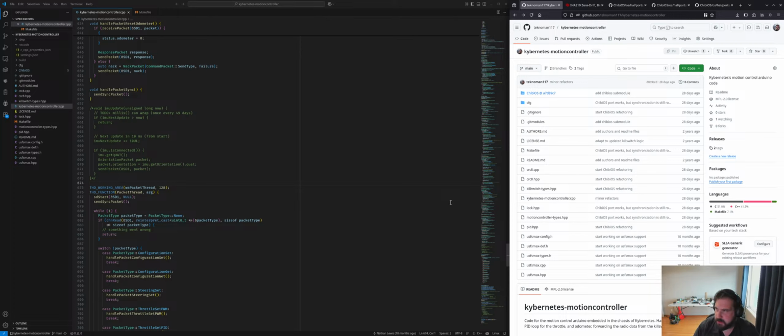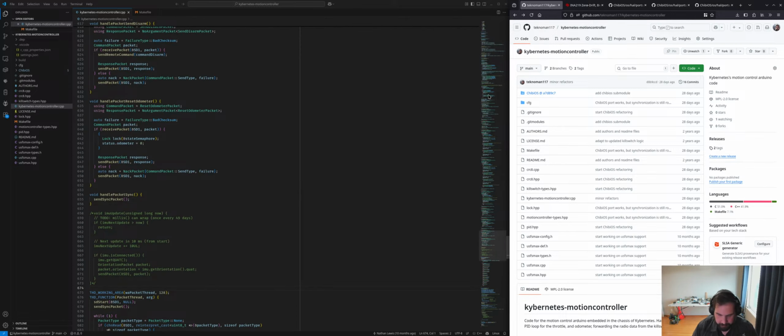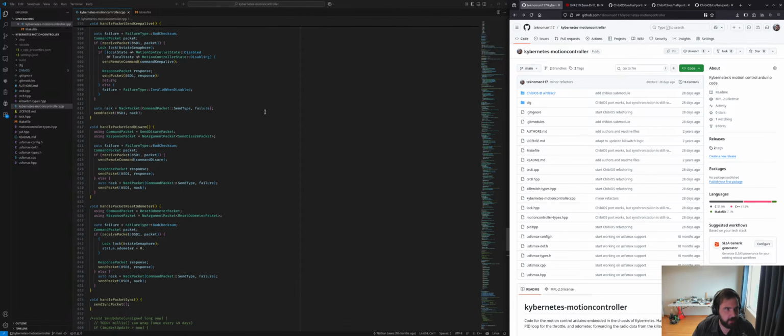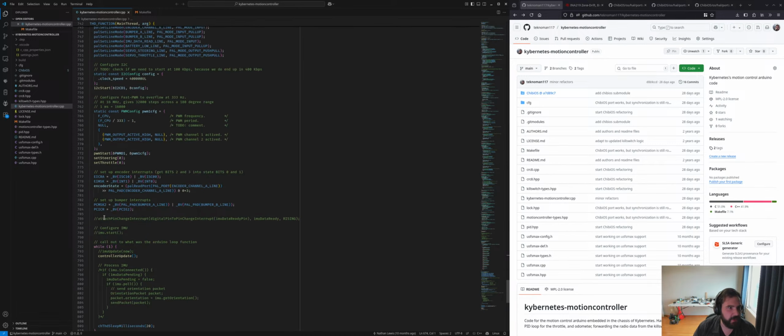As we ran into, we did have a couple of warts from last time, with the external interrupts, the GPIO interrupts on the Atmel AVR that's inside the Arduino. ChibiOS doesn't have support for what they call pad events, which are per-GPIO interrupts. It doesn't have that implemented for the AVR. So we essentially went through and manually added support for these external interrupts.